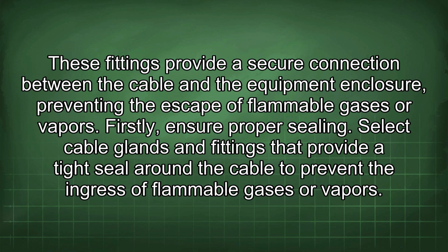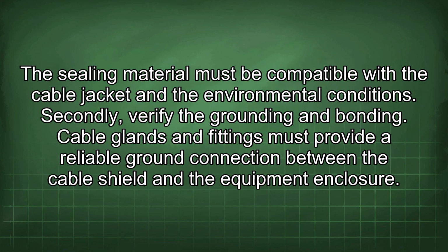Firstly, ensure proper sealing. Select cable glands and fittings that provide a tight seal around the cable to prevent the ingress of flammable gases or vapors. The sealing material must be compatible with the cable jacket and the environmental conditions.